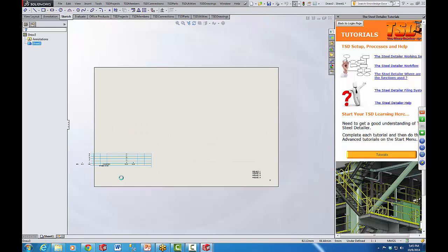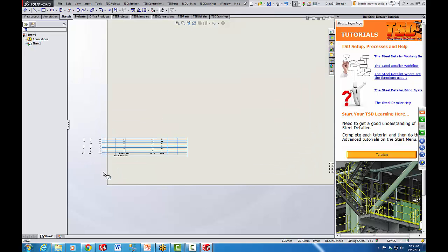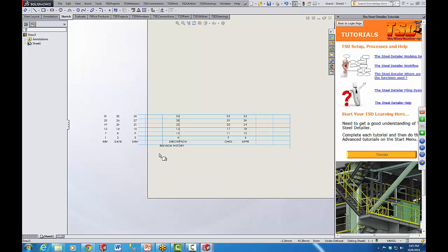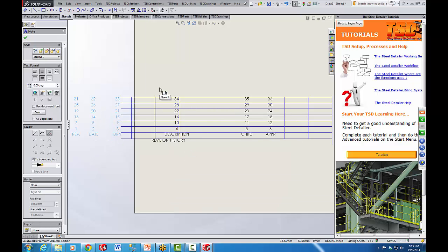Now, for some reason, I don't know why SolidWorks does this, but it does. Notice how everything's shifted. It's a pain. But anyway, the reason I numbered it is so that I can select them. And you can see that the order of the numbering is crucial as well. So I'm just going to select this information here, and holding my Control key down, select that, and then select that. And now this will allow me to position this where I want it. Okay, that's a good spot.